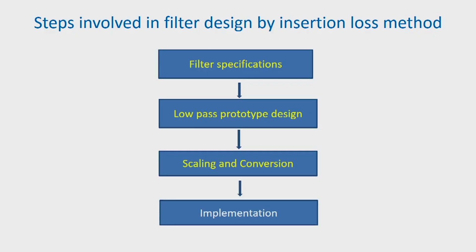The steps involved in filter design by insertion loss method are: we start with some filter specification. In filter specification, we specify the cutoff frequency, if it is a low pass or a high pass filter.